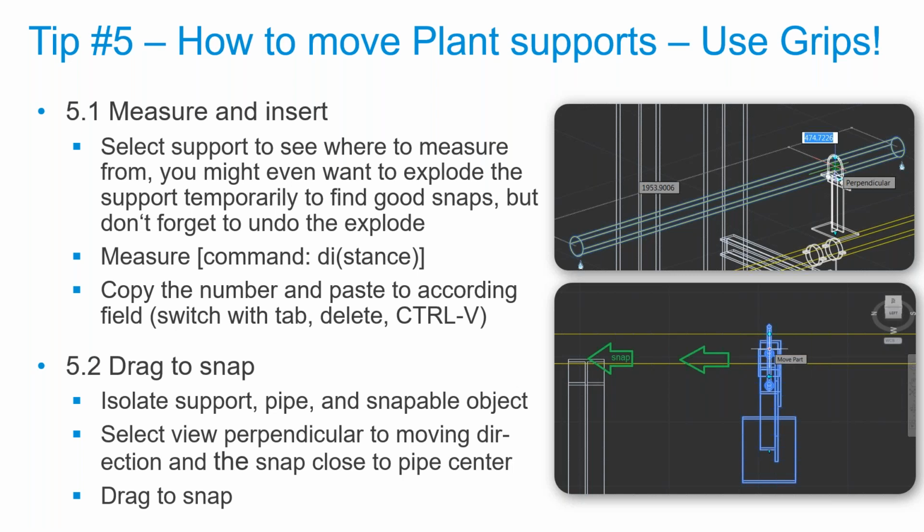And you'll see that too before you do the support on support. So if you make a mistake in selecting with that, if you see that drip icon, then you know you've got to go back and maybe do that again until you get that drip symbol to go away, and then you know that those supports are connected together. And then yeah, same thing on the pipe runs there. Good point. Yep, thanks, Jason.